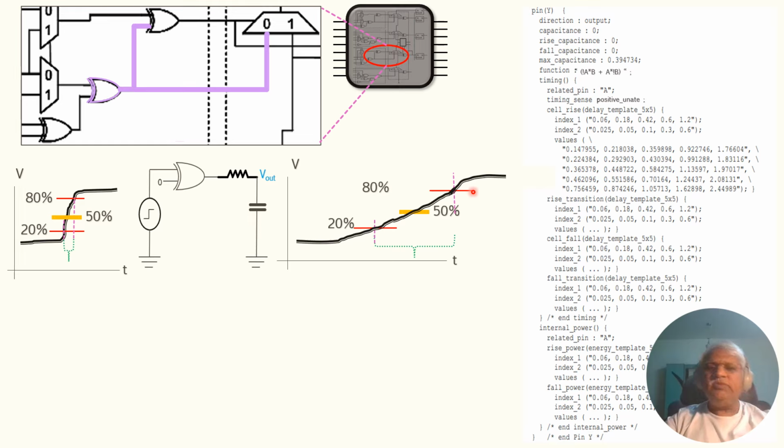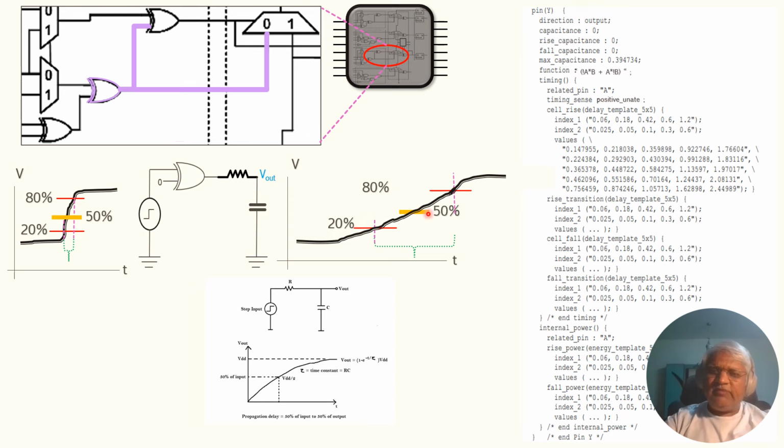This is the same thing as if you take the RC component with a step function, it will grow in an exponential manner. Same concept we studied earlier in BTech. It will grow exponentially but very slowly, because now the RC time constant increased drastically, hence it is taking a longer time to reach. Hence, this is now becoming a very easy target. That means it will become a very easy victim net.